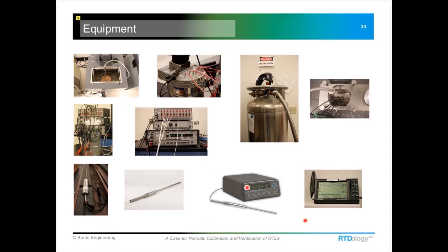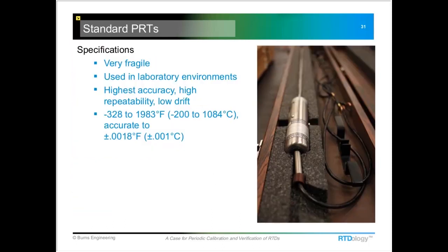Typical thermometer readout, and a lot of laboratories need to track humidity and temperature in the lab, and this meter here would be doing that. Humidity and temperature can affect the accuracy of some of the higher end calibration equipment. So that needs to be tracked and recorded, and if it's an accredited lab, that information is looked at and evaluated during an audit, for example.